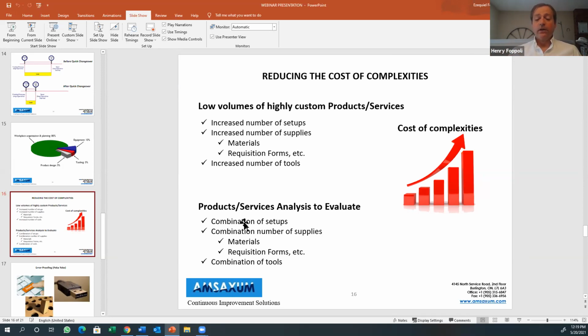That was a huge expense in setup times, in materials, etc. So what they decided to do was to standardize on 5 blocks. They said, we're going to accommodate all our molds within these 5 sizes of blocks, and we are going to manage the cooling and all the other features within these standard metrics.